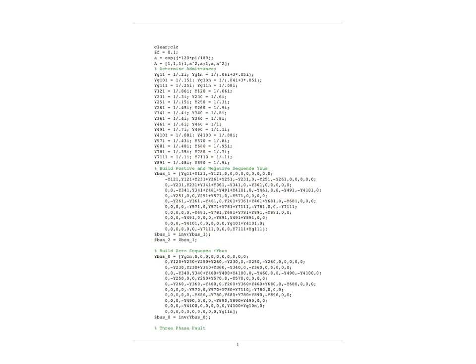And here's my MATLAB script. So I included a fault impedance, but you actually don't need to include that. You can ignore that. You can set that equal to 0. And that doesn't affect the Z-bus calculations. That's just going to affect the fault current calculations.